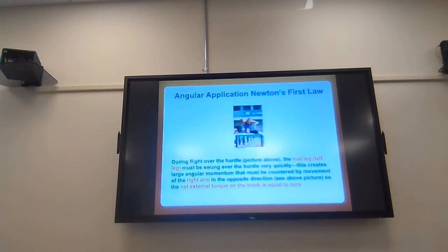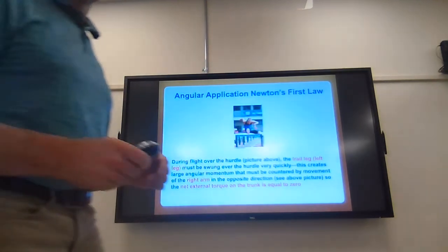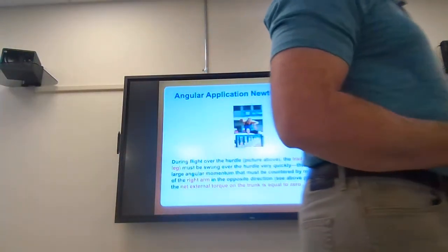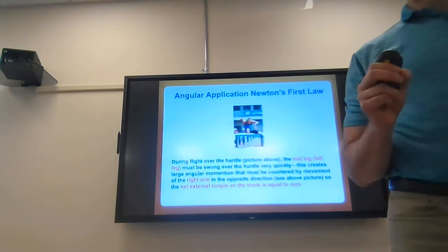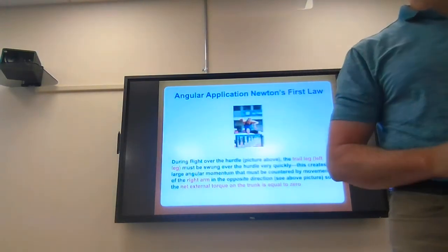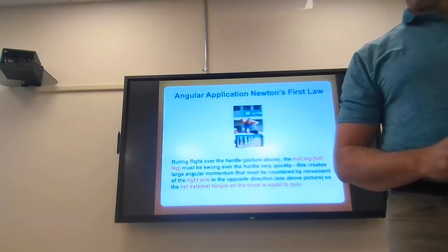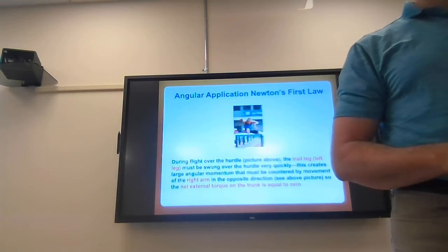Yeah, and we know that because in that formula, radius of gyration is squared. So if we double the distance between the axis and where the mass is concentrated, we quadruple the angular inertia because that radius of gyration is squared. So I is equal to mass multiplied by, what's our symbol for radius of gyration? It's a k, so k squared.